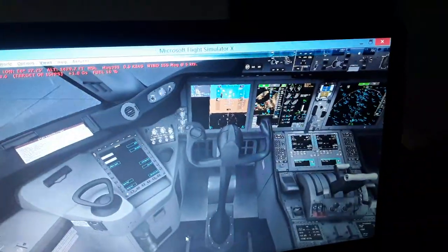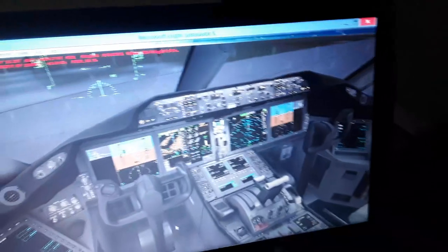So in the navigation display we have the terrain and weather reflections from the weather radar. You can see the terrain map with the airports, also the navigation aids, the VOR stations, the ADFs, the NDBs, and the waypoints, which are horizontal and vertical navigation fixes. You're going to have to traverse some waypoints as we fly. So you will see how we're going to do that also.